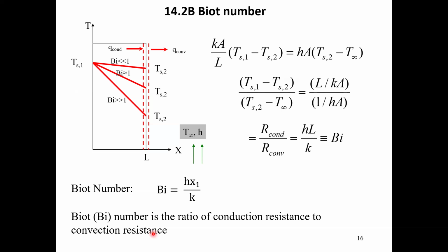In all these cases of unsteady state heat transfer, the examples we saw, we have some material that needs to be heated or cooled. So energy is going to get transferred from that material via conduction to the surroundings via convection. At that instant, heat energy transferred via conduction within that material would be equal to heat energy transferred via convection.